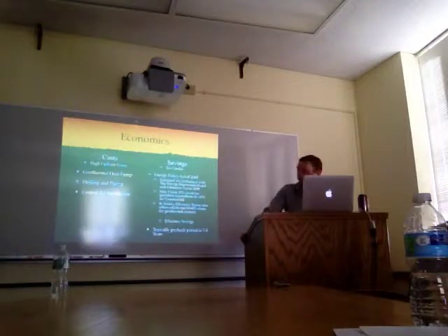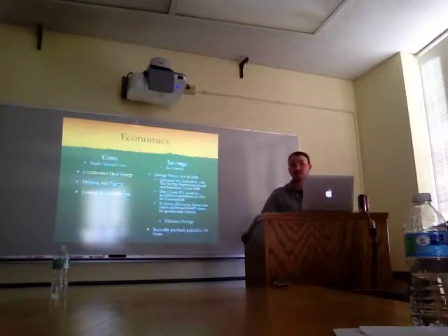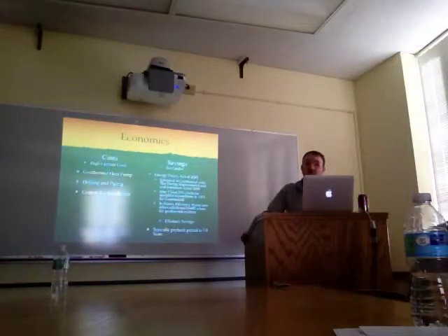The second savings and economic aspect of this is the efficiency savings. It's obviously more efficient, both because it's drawing heat from the earth and you're not paying for the resource like oil or natural gas. And a lot of times that 50 to 60 degrees doesn't need to go as high in temperature, so the electricity needed to run the geothermal heat pump is a lot lower. So you do need to use electricity to run the pump, but it's typically very, very low, especially for the amount of heat it generates. And that's estimated to have a payback period of only 7 to 8 years, and that's with some decently efficient systems. If you're replacing, for example, electric heat, that can be cut down to like 3 to 4 years.